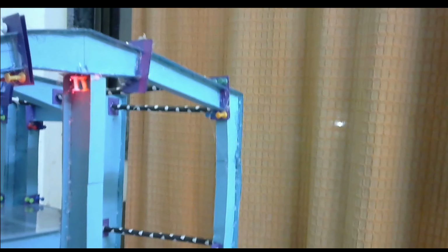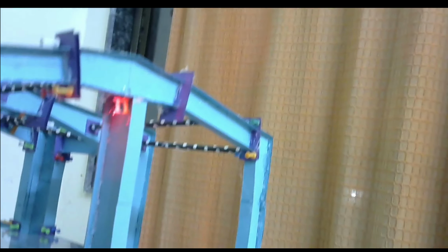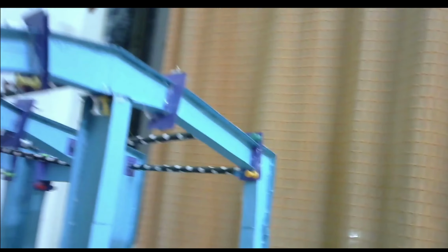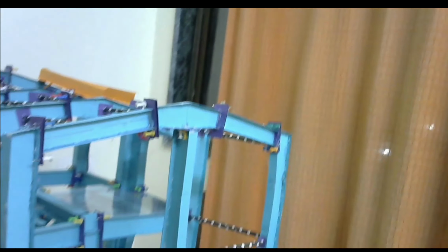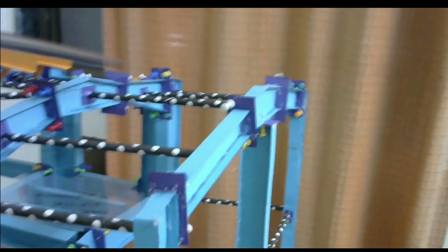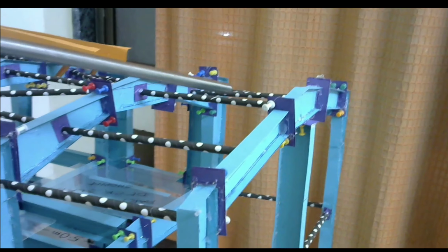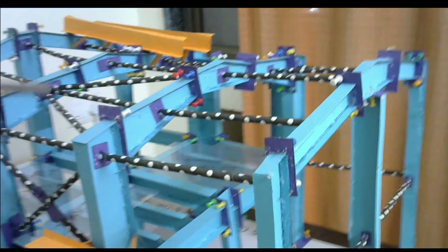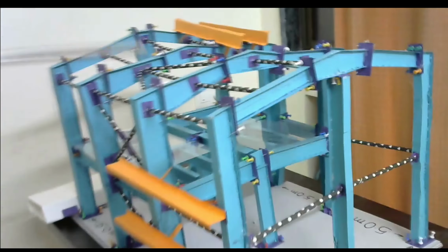The bolts are within the flanges. It is not outside the flanges. So this is actually a pin connection by design assumptions. But this pin is being restrained at the top. So the forces are traveling here to the roof braces, then to the foundation through the eave braces.